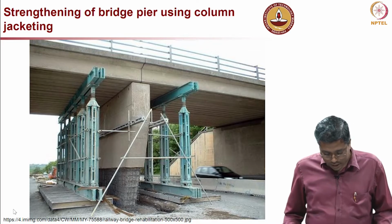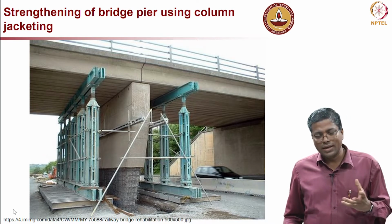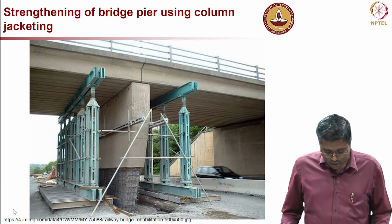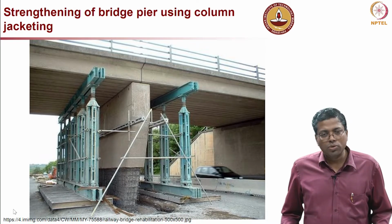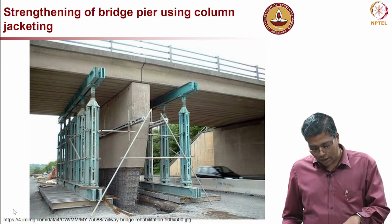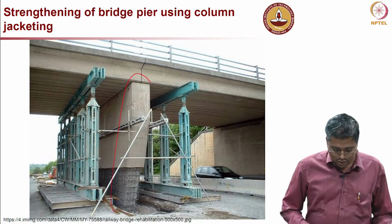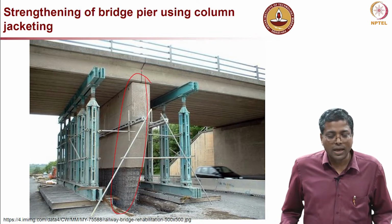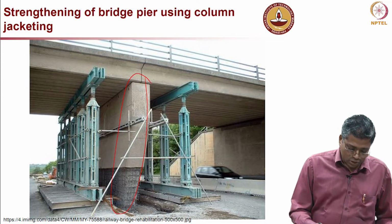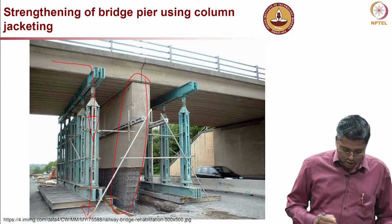Now, this is another example. In the previous one, the support system was not really a heavy duty support system, because that was just a footpath type structure. Here you are talking about a huge load, where the girders load directly. As you see in the picture, the column system or the pier is not really experiencing any load. All the load from the girders is directly transferred through these props, so the load comes here and goes directly to the ground.